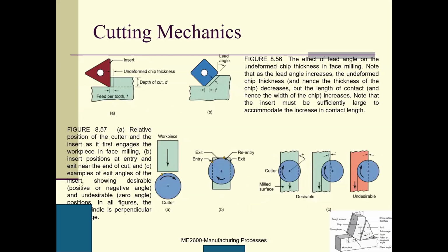So, cutting mechanics. Here is the insert. These are the undeformed chip thickness, the depth of cut, and the feed per tooth, f. Now the effect of lead angle. This is the lead angle. For this one, the lead angle equals 0.